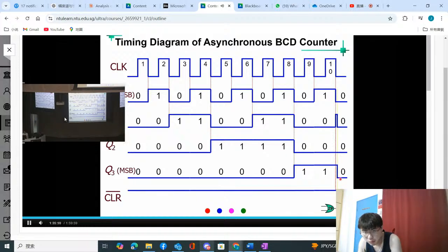So it will not be affected so much going from 1 to 0. But Q1 actually goes to high already, then goes back to low. So it goes high, then goes to low. In here we call it a glitch. Okay. So if you're not careful in your design, this glitch might make the output signal go to 0, 1, 0. Instead of supposed to receive a 0 throughout, now it becomes 0, 1, 0.